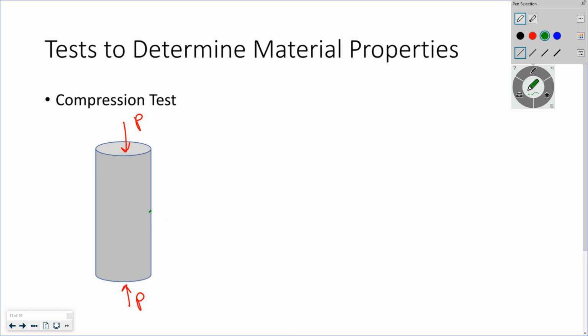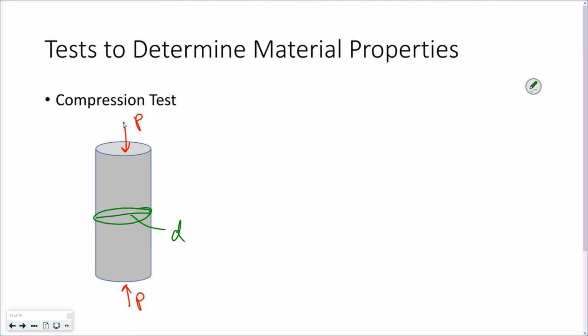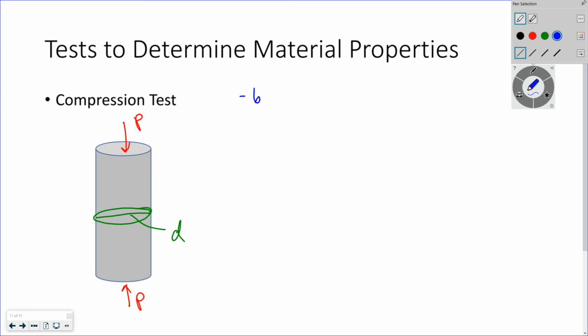Our cylinder has a certain diameter. I think it's usually about 4 inches, or 6 inches. That's right, 6 inches. I have it actually written down. We do 6-inch diameter by 12-inch height cylinders.